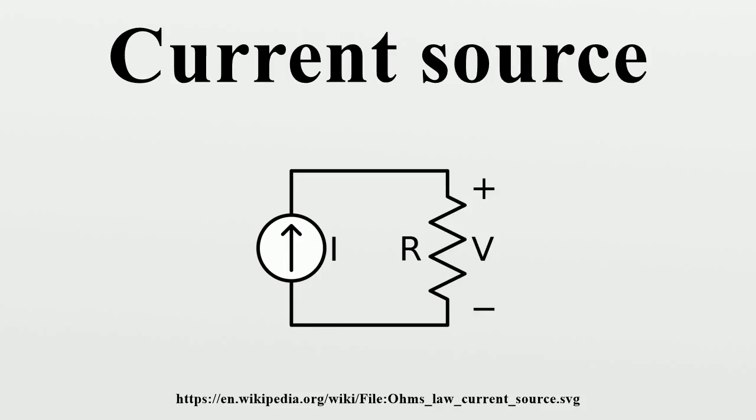Transistor current source with diode compensation. Temperature changes will change the output current delivered by the circuit of Figure 4 because VBE is sensitive to temperature. Temperature dependence can be compensated using the circuit of Figure 6 that includes a standard diode D in series with the Zener diode, as shown in the image on the left. The diode drop tracks the VBE changes due to temperature and thus significantly counteracts temperature dependence of the CCS.